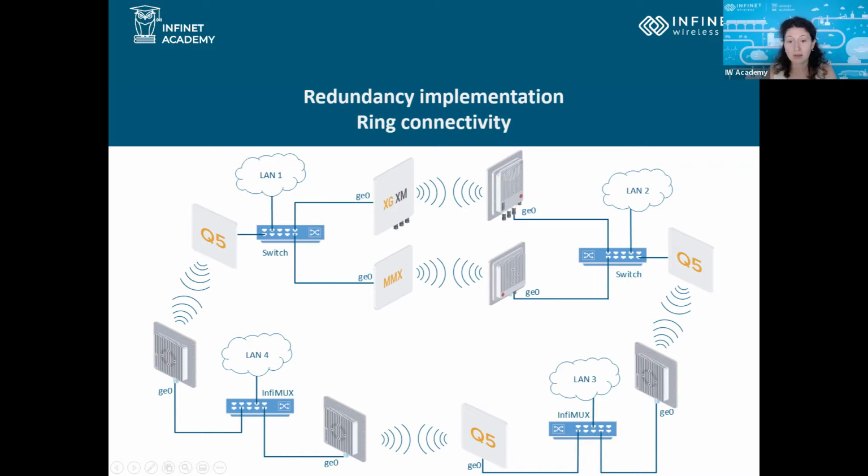This is a realistic redundancy implementation, but the scenarios are very vast and can be adapted to the needs of each project. What is very important to keep in mind when introducing redundancy is that by providing backup connections, we create loops in the network. Redundancy means therefore loops, so unless we use a proper configuration method, we will be facing broadcast storms that cause unavailability instead of increasing the availability, which was our initial main scope.